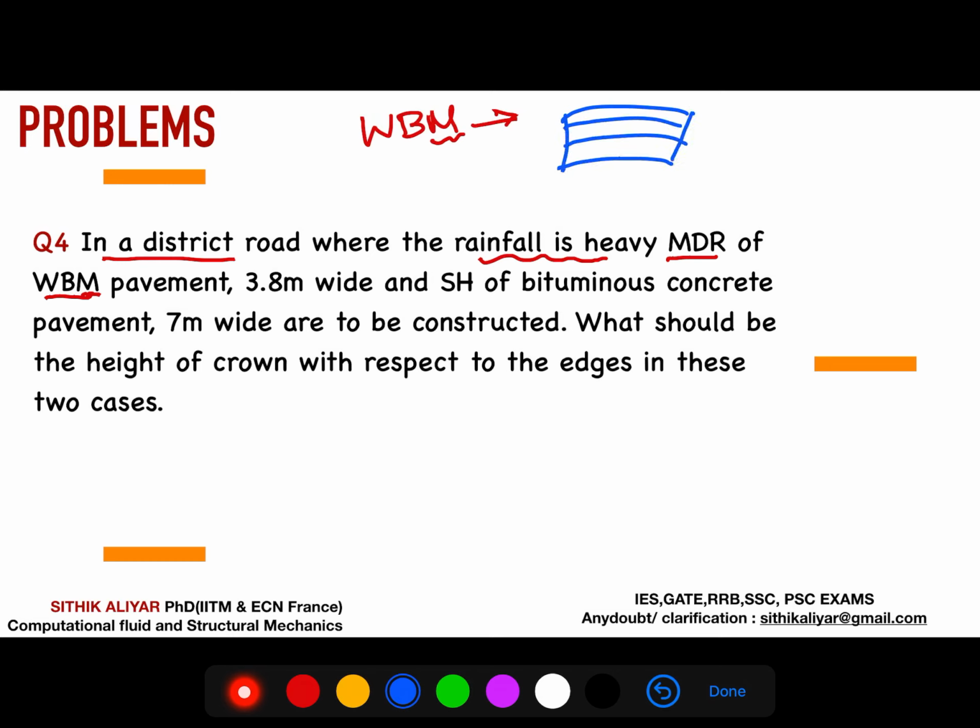So we will have 3 layers of 1 in 36 slope, something like that, for both subgrade and top, and 50 mm aggregates at the bottom, lesser value, and very small aggregates at the top. So macadam road is exactly the same, but they will not have a top surfacing, either concrete or bitumen. The surface will be without dressing.